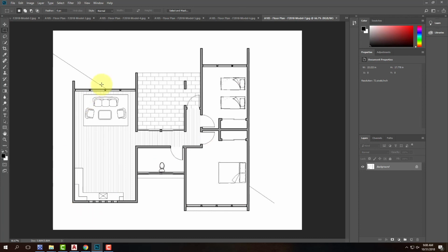So the purpose today is to fine-tune your floor plan. You'll have time to continue working on your floor plan itself. If you're not quite fully developed yet, you can have time to work on that. Then I'd like you to try to bring in some blocks, set up your line weights and your layers. Ultimately, try to do some hatching, see how that works for you. If it doesn't work, remember you can leave that part off as it is optional. And then ultimately, we'll get to the point where you have your floor plan ready for next class.